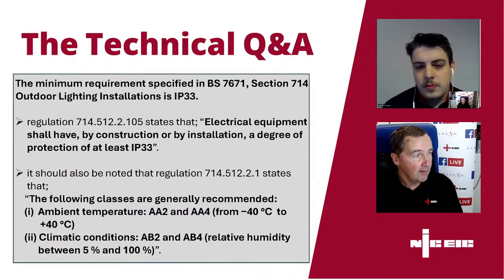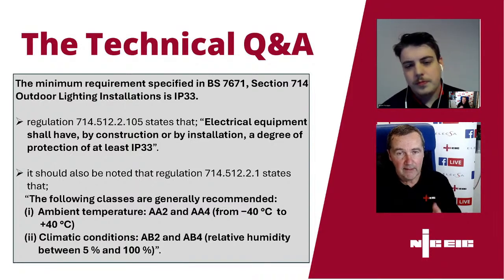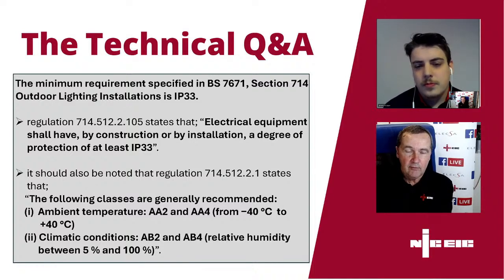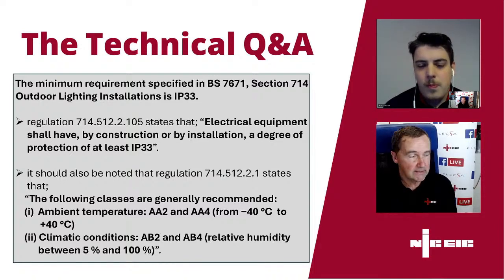You can still go ahead and, as the engineer has said, have a look at section 419, which talks about being able to bond everything in that area. Then hopefully when you get to the next sub board or distribution board, your currents are lower and the protective devices will be able to achieve their maximum Zs. So yeah, it's doable and it is a common occurrence.